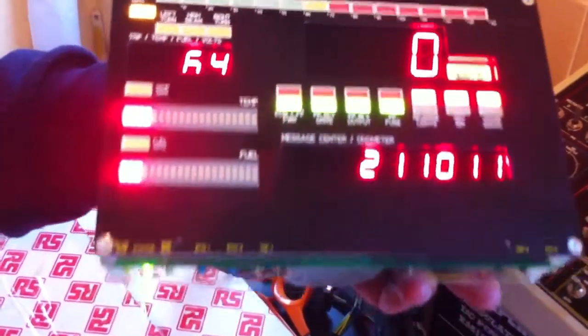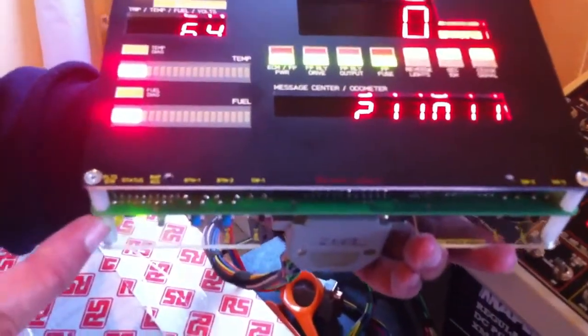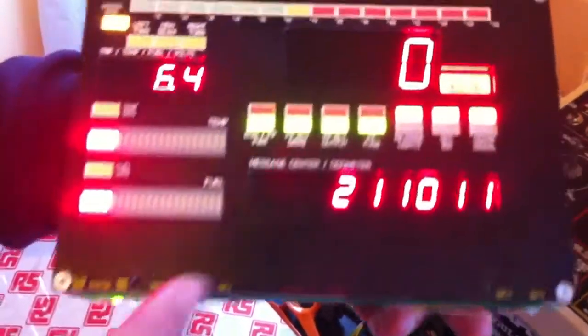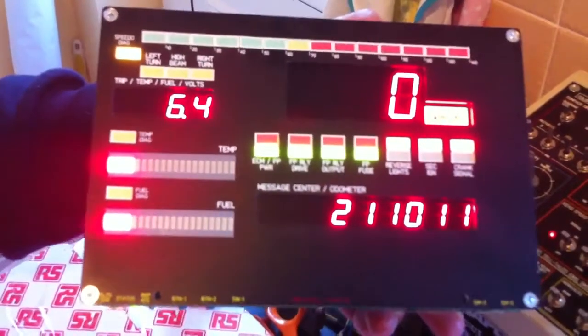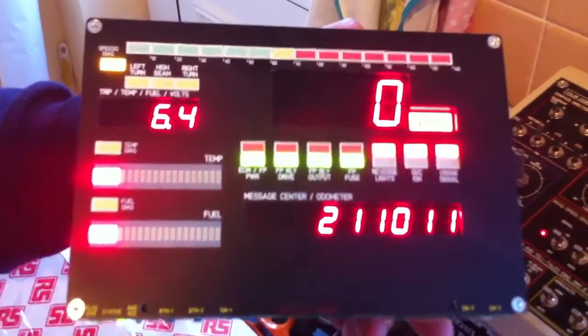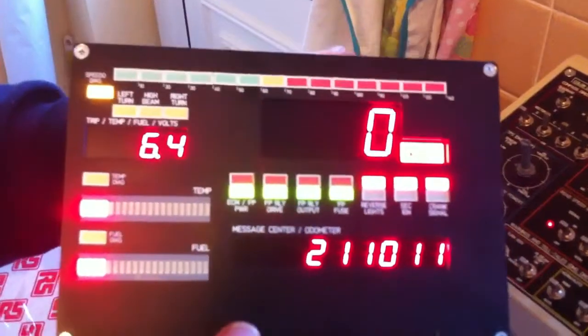And you can see that back in normal running mode now, the yellow LED has cleared, the status LED is back on green, and the F has disappeared, meaning there's no faults currently existing with the unit and no faults stored in memory. And that, essentially, is the diagnostic mode of DM2.